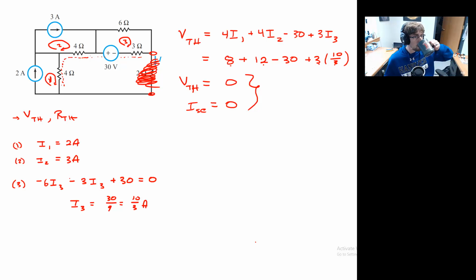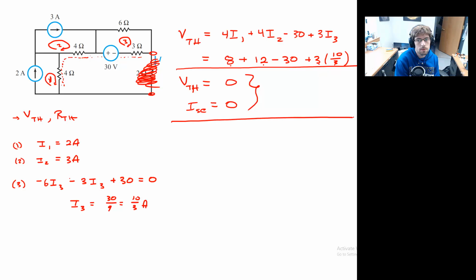I forgot about that. So we see that using the short circuit technique here isn't going to help us find the Thevenin resistance. Okay, well, let's go ahead and use that technique where we deactivate the sources. Might as well. This is just practice anyway. So let's go ahead and deactivate the sources. And what that means is that anywhere that we see a current supply, we're going to pretend that that's a break. So we break those two as if those don't exist at all.